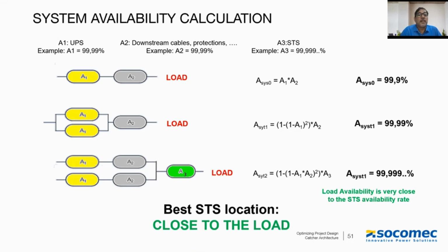Now, in fact, contrary to the concept that additional equipment added to the system means additional maintenance, if you see the resiliency part, managing the downtime in the situation of any downstream faults, the STS plays a key role here along with the UPS systems for ensuring a comparatively better availability factor for the entire setup.